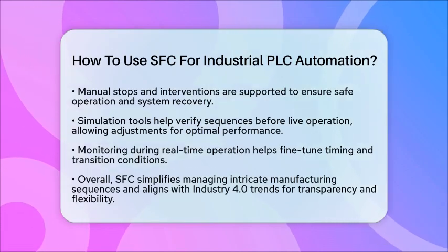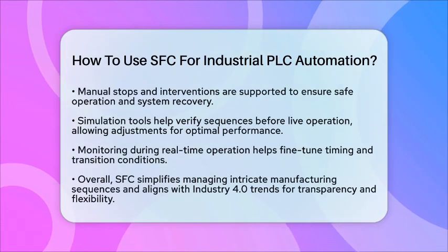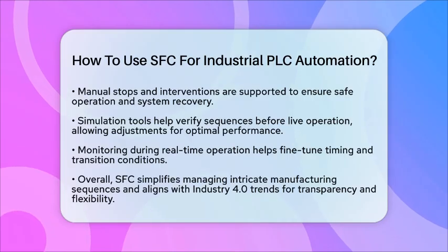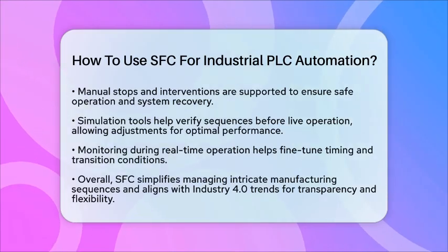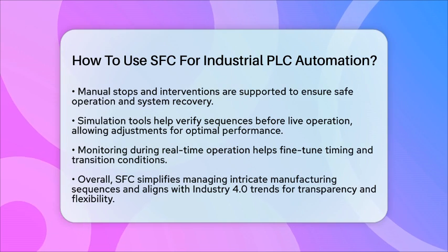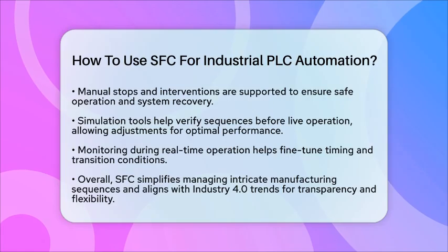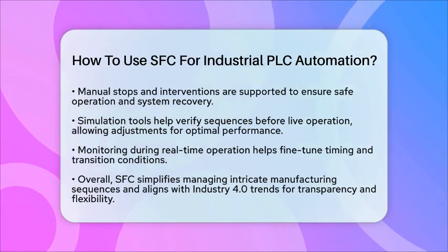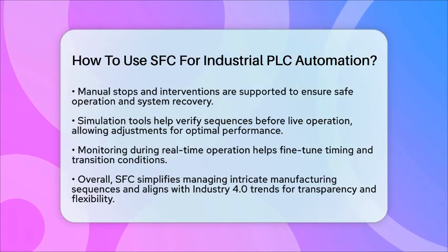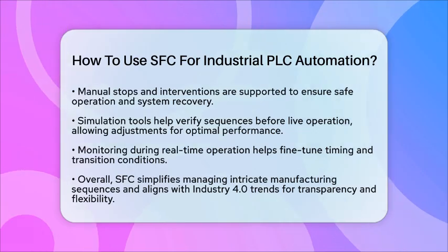Finally, testing your sequence is essential. Use simulation tools within your programming software to verify everything works correctly before running live. Watch how the steps and transitions behave and make adjustments as needed. During actual operation, monitor the system to fine-tune timing and conditions for optimal performance.